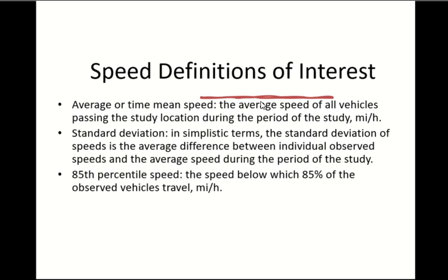So what do we do then? We take the 85th percentile of the data. The 85th percentile means the 85th highest value in the data. If we have 100 values, you arrange the data in ascending order, lowest at the bottom, highest at the top. In this order, the 85th value will be the 85th percentile. Clear? So instead of taking the mean, the value near the middle, we take the 85th percentile, which means you have crossed the middle now.